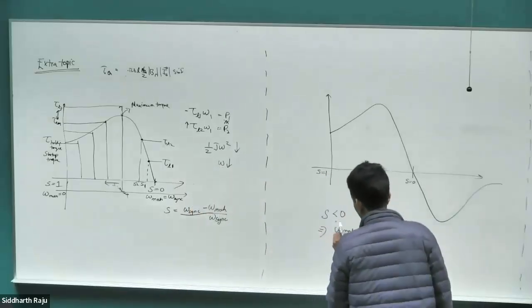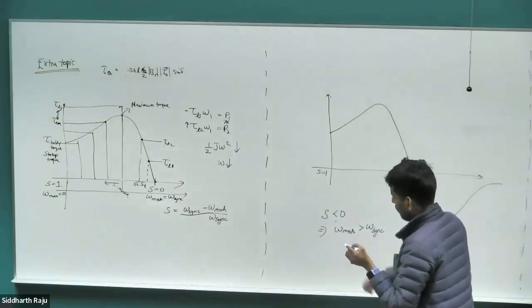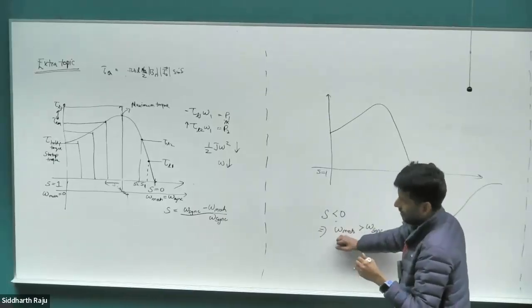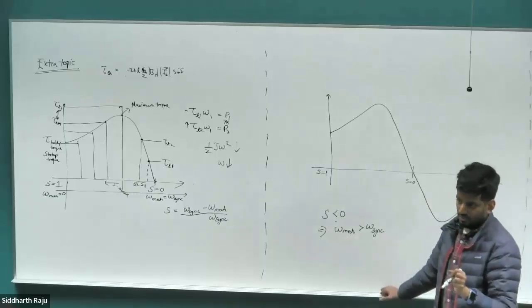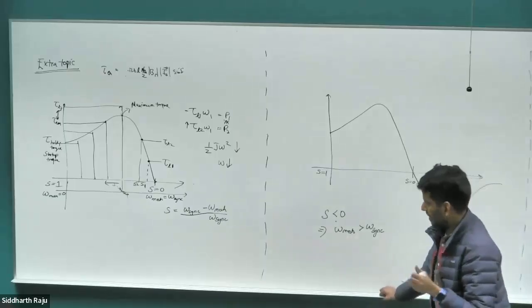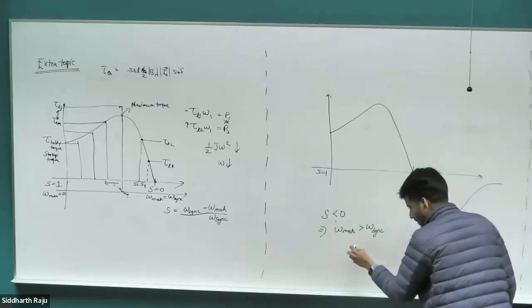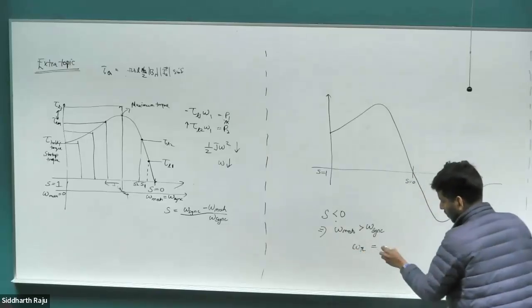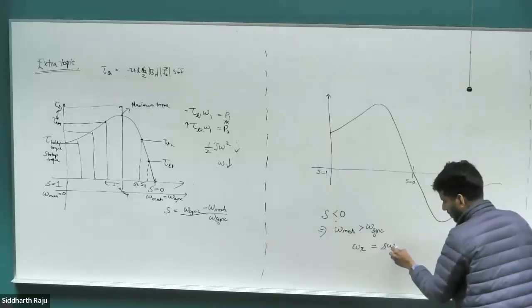But the space vectors, the EMF space vector and the rotor current space vector, all of those are still rotating at exactly the same speed as before at steady state. All right, so what's happening is, if you look at the rotor frequency, omega r, we said that was slip times the electrical frequency.